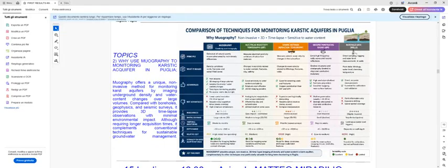Electrical resistivity has ambiguity in interpretation, and is affected by the presence of surface quaternary deposits. Also, seismic methods require expensive logistics and complex interpretation. Georadar usually has a shallow penetration, less than 20 to 30 meters.